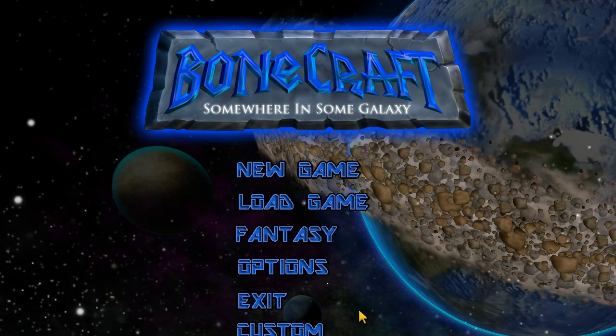Hi there. This is going to be a walkthrough of how to create a simple mission using the BoneCrafter Mod Kit tools. I'm going to make an island with an orc area and an elf area that is separated by a forest. The things that will be covered are placing objects in the world and the different ways you can modify these objects once they are in the world. I will also talk about deforming the terrain and painting it.